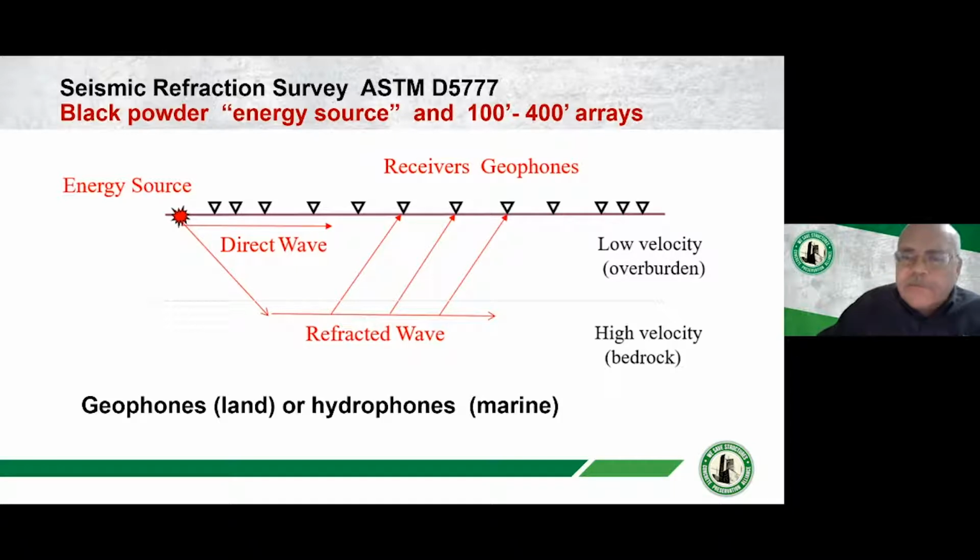General soil profiling data, but more specifically, usually we're interested in where is the bedrock. And we could do some north-south lines, some east-west lines, and actually come up with a contour map of the bedrock. Very strategically beneficial if that can be done before a subsurface exploration program. That way the borings can be strategically located to verify this.